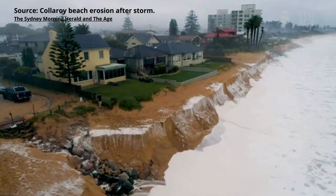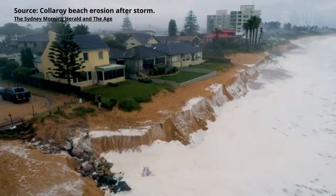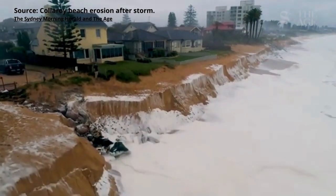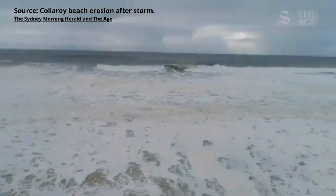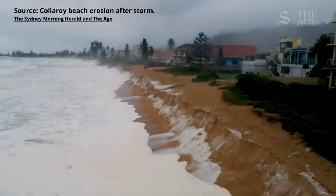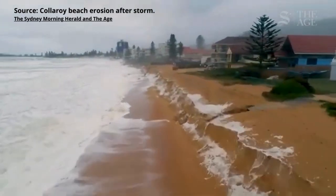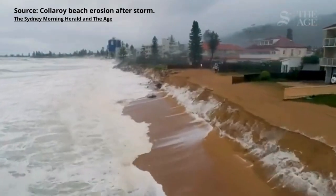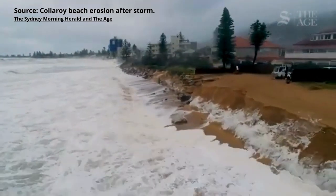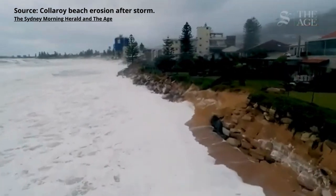It is known that storms are responsible for the most drastic and immediate changes that occur along coastlines. When this occurs, sediment transport is intensified primarily in its cross-shore component. This is perpendicular to the coastline. This causes a large amount of sediment from the back beach to be eroded and deposited offshore. As we learned, a series of groins do not help to reduce the associated offshore-directed sediment transport.